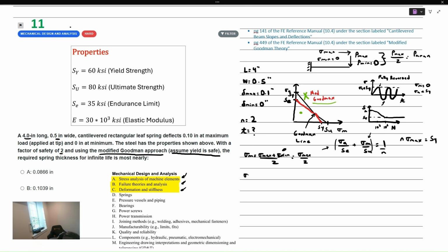What about for the alternating stress? That is just the max minus the min over 2. And that's just the same thing, right? Max over 2. And if you think about the kind of stress history that will be associated with this, we'd have something like this. A sinusoid where the minimum stress is equal to 0 and the maximum stress is this peak over here. The alternating stress is represented by the distance between the mean stress and the max, right? And that's the alternating stress, and you can see they're both equal to the max over 2.